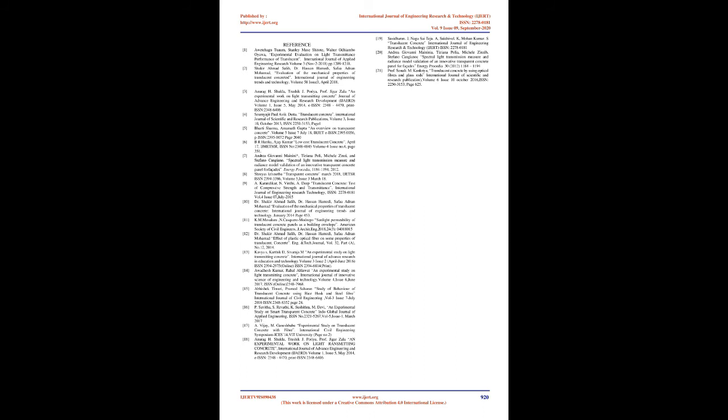Conclusions. From the whole study it can be concluded that light transmittance of up to 6.69% was achieved by using 5% plastic optical fibers. This can be further increased and light transmitting concrete can be used efficiently in green buildings. It can ensure natural light inside the buildings throughout the day. Based on compressive strength test results, it can be said that the strength of higher grade light transmitting concrete is not significantly affected by inclusion of POFs. Light transmitting concrete requires skilled labor for its production, as POFs should be properly placed in concrete, and special attention is needed while placing concrete, to ensure no damage to POFs.